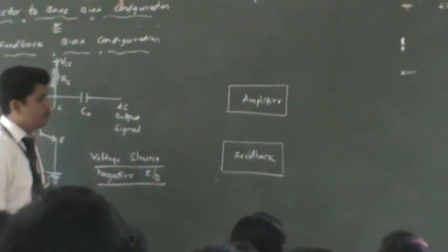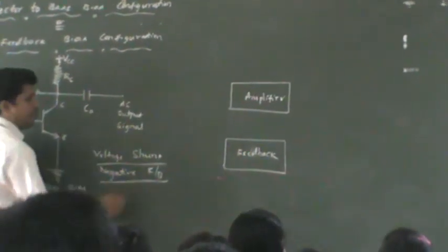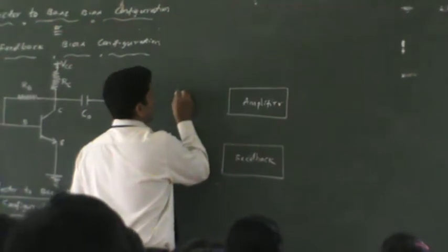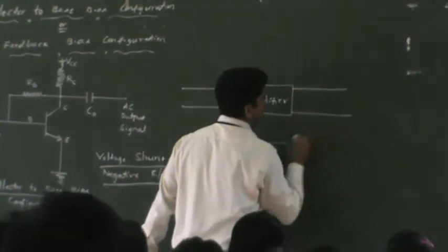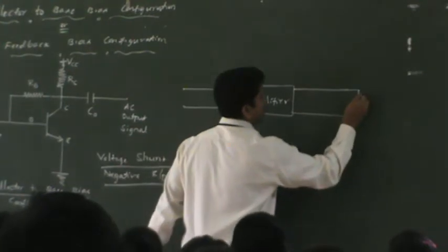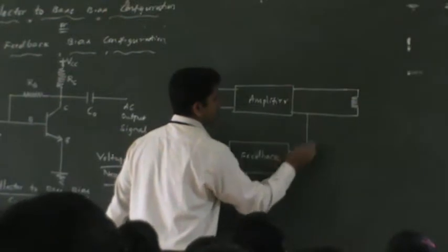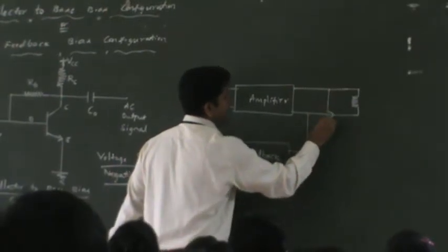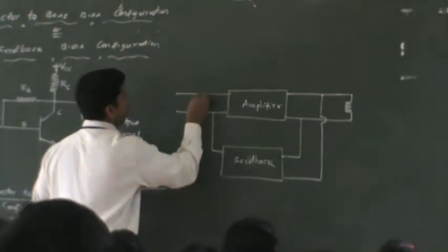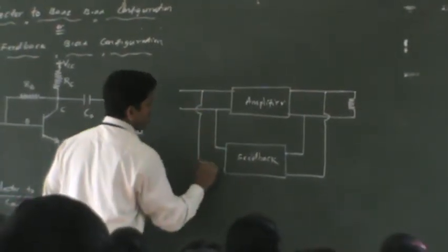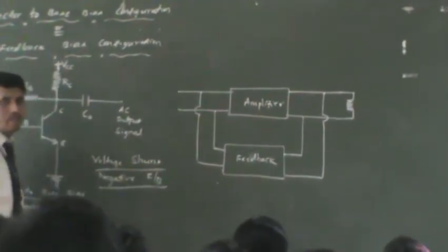Just an overview I am giving here to show that we expand this concept of voltage and negative feedback. So a feedback amplifier will have 2 inputs, 2 outputs, and here you can see that we will have a load resistor here and the amplifier output. We will sample this voltage in parallel, that is called the shunt, and the same thing we will provide to the input.